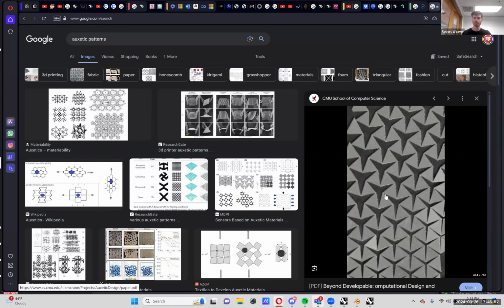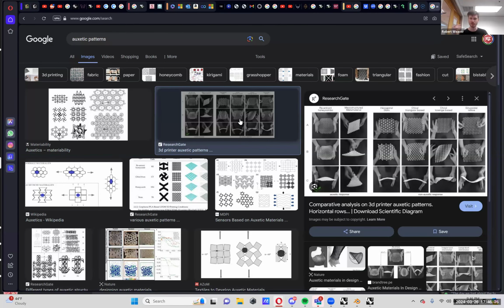I mean, it would over time. I think any plastic would, the more times you stretch it. I think it just depends what the angle of the joint bend is. With different patterns, it's probably different bends. But we have had students in the past in the AMP lab experiment with some kinds of patterns like this, and they were just using PLA, and it would still mold to whatever form you put it on pretty nicely. And we've had these for like 8 years. So it works pretty well. But it'd be something to test. You can do the same pattern in TPU and in PLA and see what the stiffness between the two is, and maybe play with that a little bit.